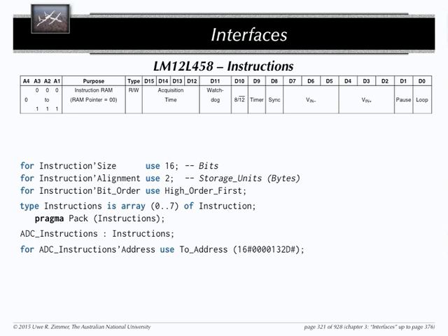Then you can define an array of these instructions, here from 0 to 7 to refer exactly to the instruction numbers as they are appearing in the device itself. And that's a bit clunky. I wouldn't use a pragma today anymore. You can use attributes for that, but you can also use a pragma for that to tell it that if you allocate this array, no gaps.